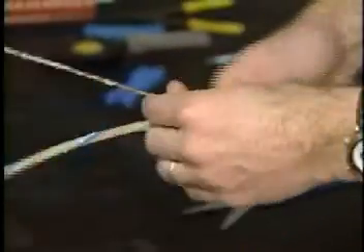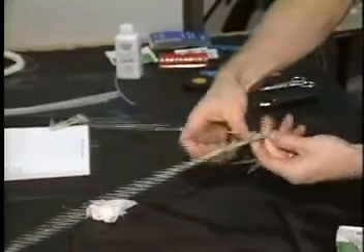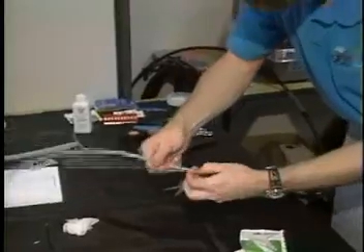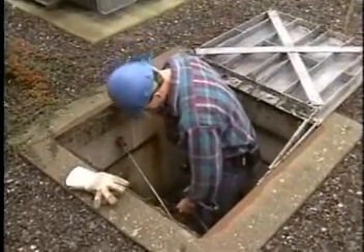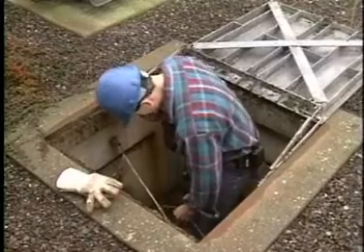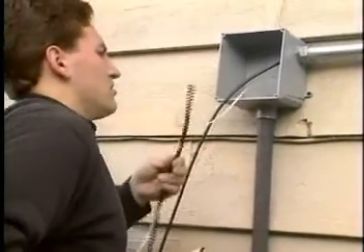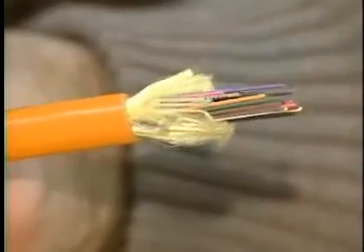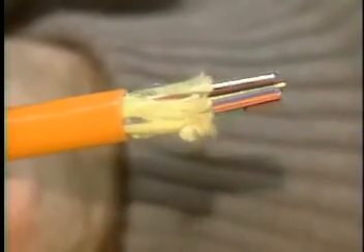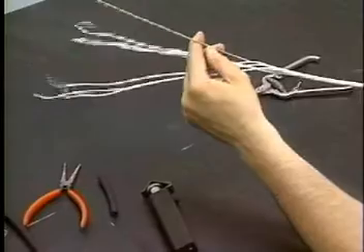In order to effectively pull in a cable without damaging the fibers, you must identify the strength members of the cable and attach it to the pulling line. Several methods of attachment can be used depending on the cable structure. With direct attachment, the cable strength member is tied directly to the pulling fixture. If aramid yarn is present, it can be used for direct attachment or provide added grip with indirect attachment methods.